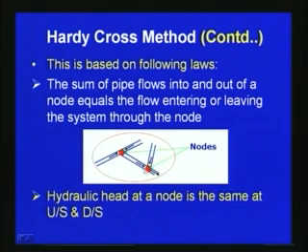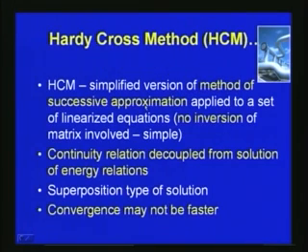So, if you consider this as the node, then whether upstream, that means here or here, the hydraulic head is the same. Based upon these assumptions, or these basic laws, which are fundamental laws with respect to continuity, the Hardy-Cross method is based upon these two basic laws. In the Hardy-Cross method, as we discussed, it is a simplified version of the method of successive approximation. We have seen that the generalized equations we can solve through successive approximation.